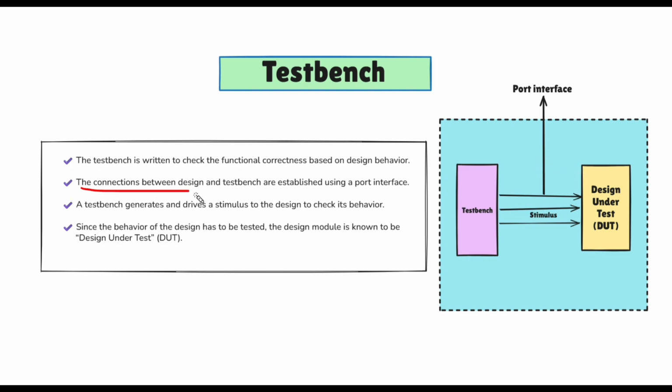Okay, next point is the connection between design and test bench is established using a port interface. So to test that DUT, we connect our design to the test bench through the port interface. This is the only medium through which we can connect to our design. Okay, a test bench generates and drives a stimulus to the design to check its behavior. This is the main point here.